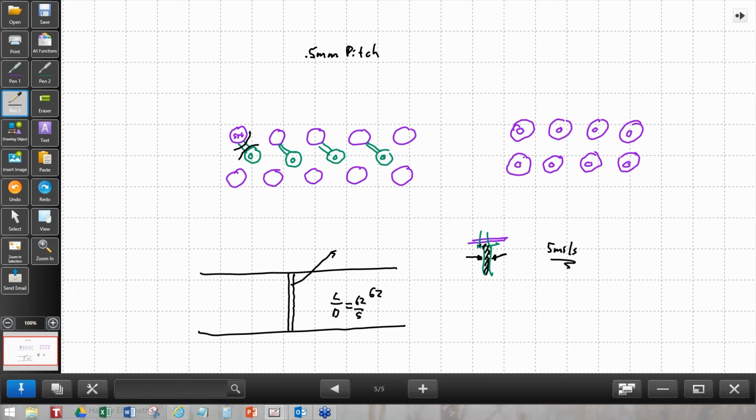Why is that? Well, if you're plugging with a material that's conductive, then it's hard, because typically they'll grind up something, powder aluminum or usually silver, and they'll put the silver inside a binder of epoxy or whatever material they're using, and then they'll try to pump this down the hole. How do they pump it down the hole?